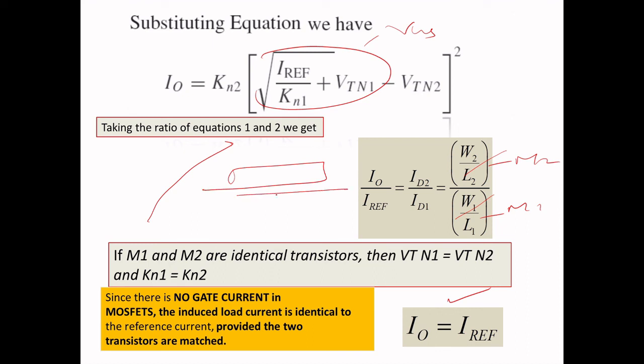Another thing: mostly in the MOSFET, only the length will be modified. You can see this is your length, the length of the channel. You consider this a channel, in between your source and your drain. This is your length and this is your width. The best method is changing the length. The width by length ratio is a very important parameter in the current equation, so based on the width and length parameters only, the current is determined.